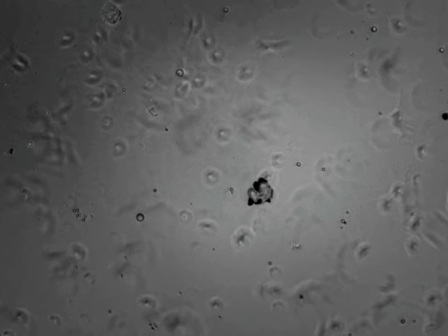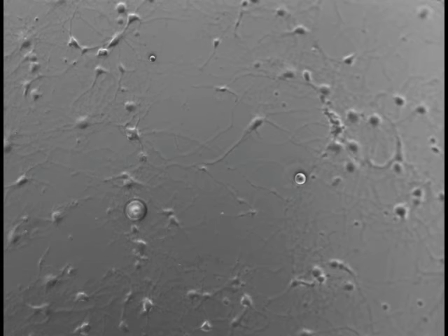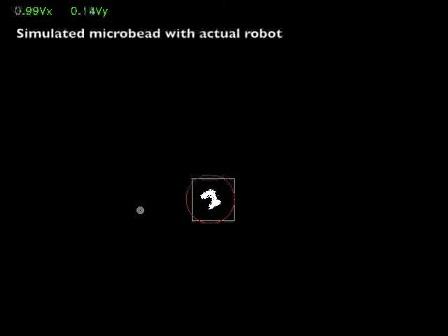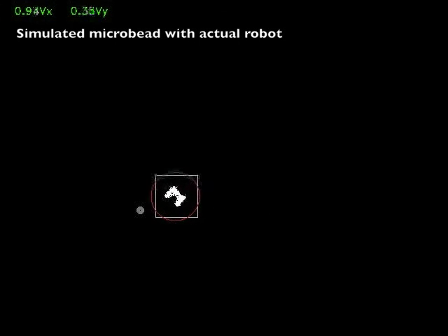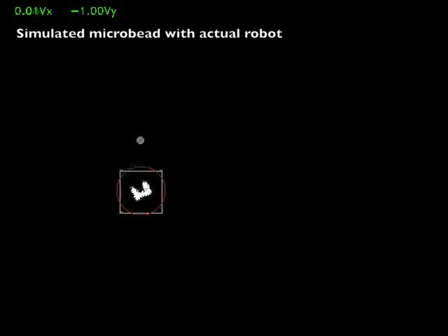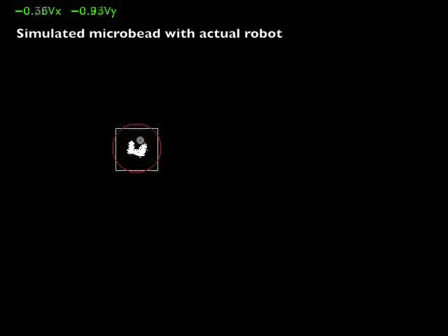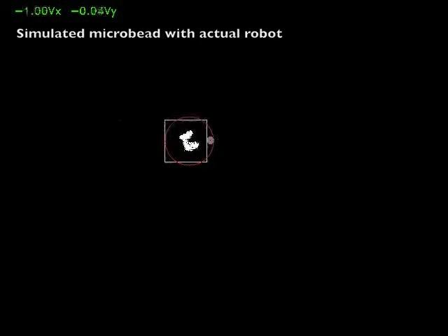For tracking the robot, the microscope illumination method is switched to fluorescence mode. The magnetic transporter is fabricated using an autofluorescent material, and the beads are tagged with fluorophores. Fluorescence-based tracking is an effective method to filter out all objects in the image except for the bead and the robot, and in turn greatly reduces the complexity and computational cost of tracking algorithms.